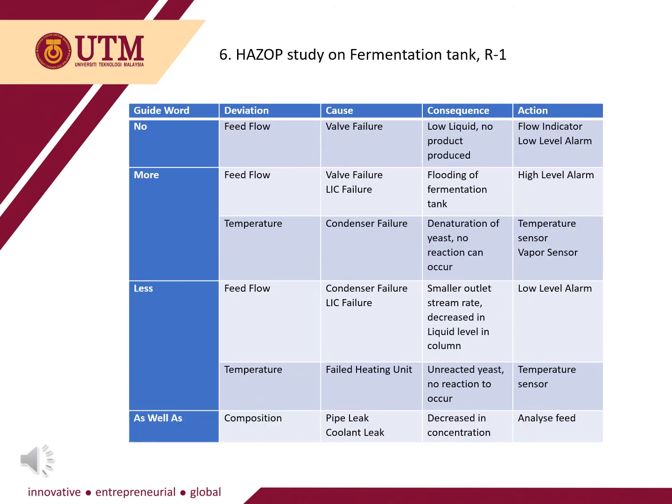So, moving on to the hazard study on the fermentation tank. What if there's no feed flow due to valve failure? Low liquid or no product will be produced. So what we can do is install a flow indicator and low level alarm.